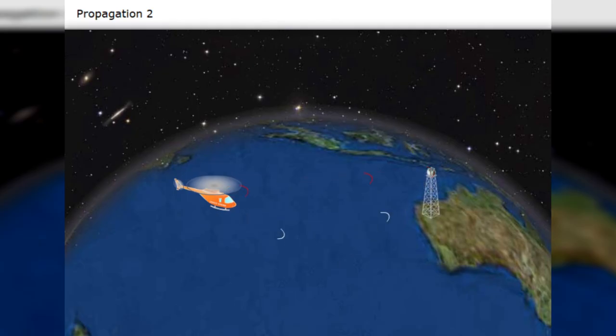Seasonal variations. During summertime, increased UV radiation causes change in the ionosphere, and therefore summer HF communications usually operate on higher frequencies than those used in winter to cover the same distances. Solar cycles. Solar activity varies the amount of radiation received by the Earth and will affect HF propagation. Solar activity has an 11-year cycle, with the peak of solar activity requiring the use of higher frequencies. Solar flares can cause complete blackout of HF radio waves, though these are rare and typically last for very short periods.